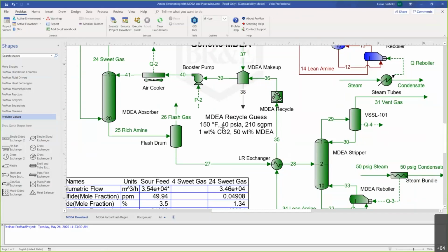Really common rule of thumb is, now this is in English units unfortunately, but it's just really nice. We say for MDEA, and this is pure MDEA without piperazine, we tend to say like 1 pound of steam per gallon of solvent, and you can convert that to metric units. If you think about it, a gallon is about 4 liters, and a pound is about half a kilo.